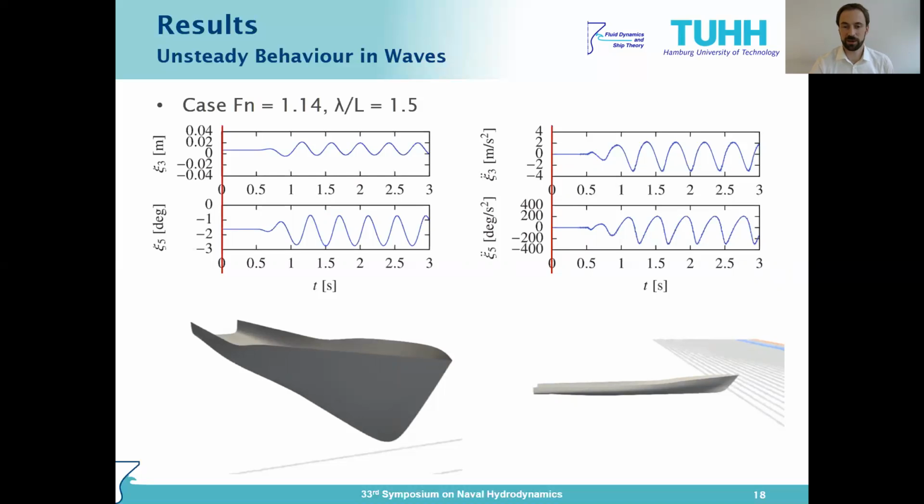At the beginning of the simulation, all the cross planes are in front of the hull, and then the hull starts to move forward at the prescribed forward speed into the fluid domain. As soon as it has passed the first section completely, the equations of motion are solved, and waves are also accounted for in the cross sections and in the boundary conditions when solving the flow.